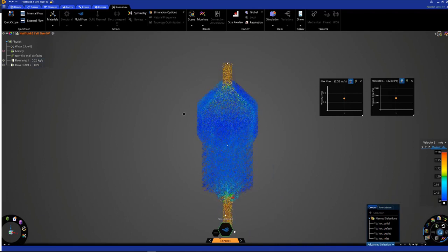The last thing I want to call out is the fidelity slider at the bottom. Right now it's just set at its default. I'm going to put it closer to its highest fidelity, or most accurate. If you're unaware, the slider will always be available. What changes, however, is the voxel size that is available, and that voxel size is determined by the power of your graphics card.